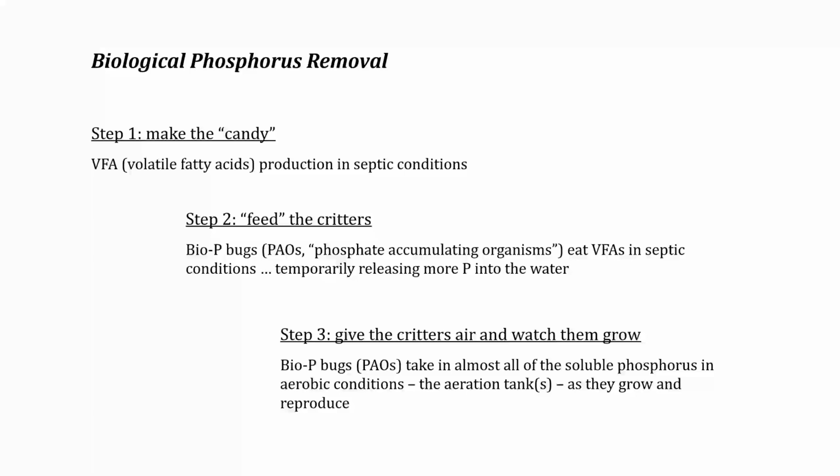I could put a step 4 in here, which is don't let them re-release the phosphorus, because that becomes one of the nuances of phosphorus removal. It's oftentimes possible to get through all 3 of these steps, and particularly in warmer water, if you let the solids settle out after aeration. Prior to aeration, I'm going to talk about tools for allowing solids to settle out on purpose. But after aeration, after we've energized and gotten the organisms to concentrate phosphorus in their body, if they settle out too long in warm water, they can re-release the phosphorus.